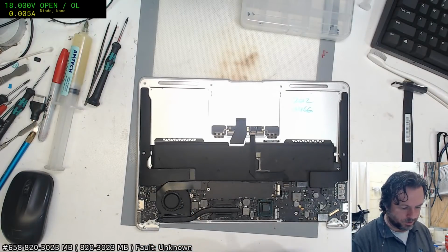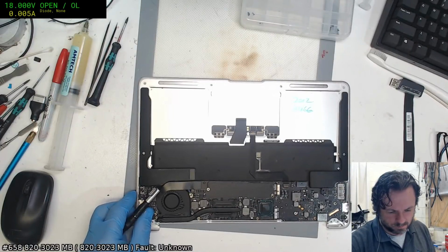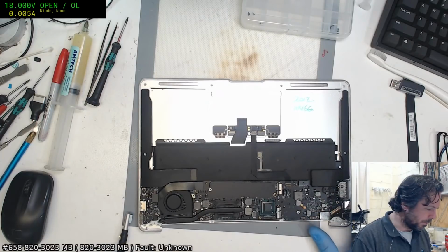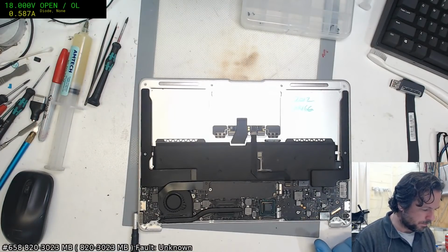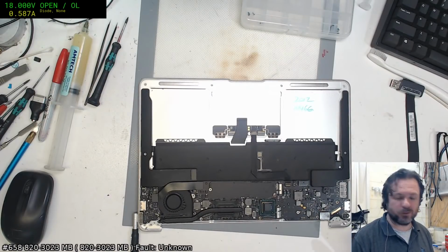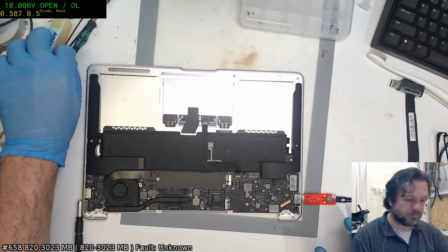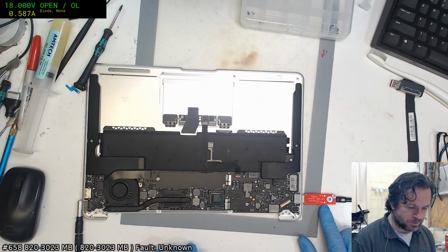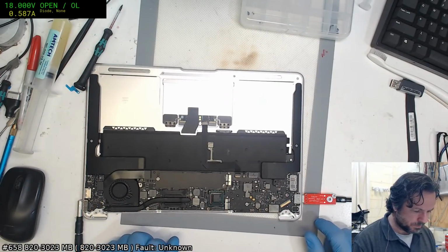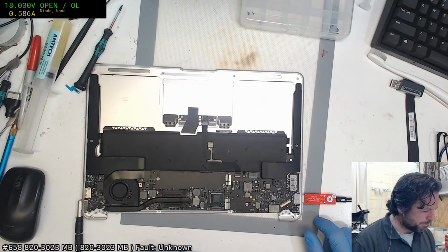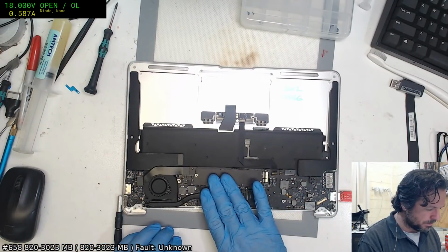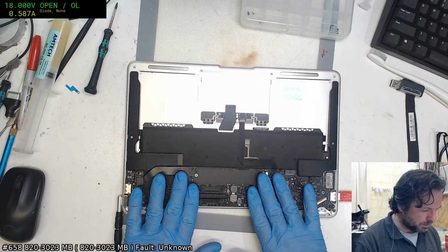We don't want that one in there, we want the chipmunk in here. Surging circuits, that's probably about right. Okay, so you can't see that, right? Okay, so we've got 5 volts, we've got power, we don't have a fan spin. That's a little bit different. What's our current? 586. Something is getting hot here. The CPU slightly.